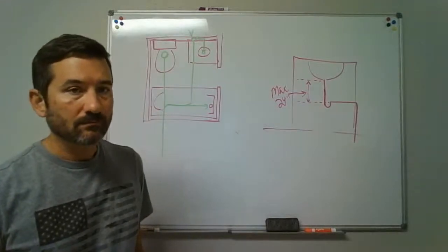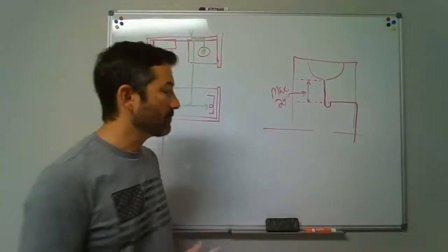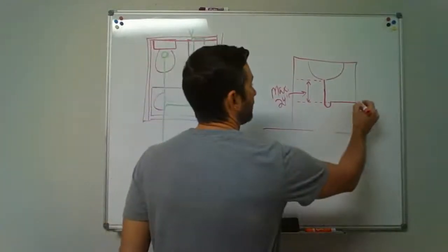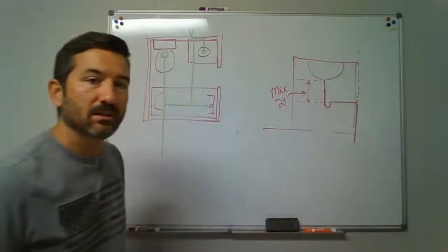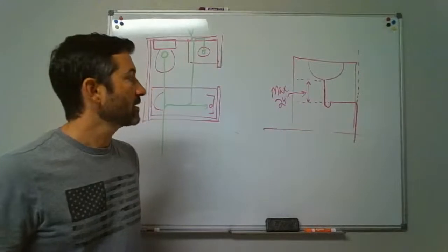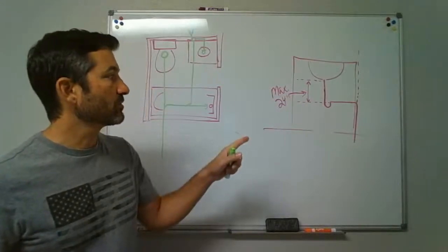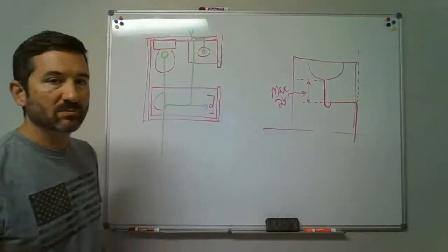So when I want to go down, I'm going to have to go up with a vent. When I turn up with a vent, it allows me to then drop the pipe right off, okay? So because of those rules, it's going to make the vent always be on that sink.